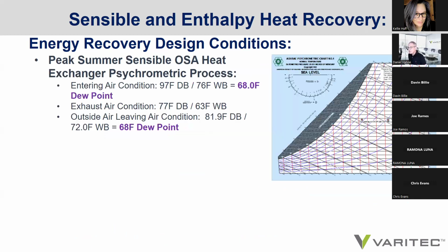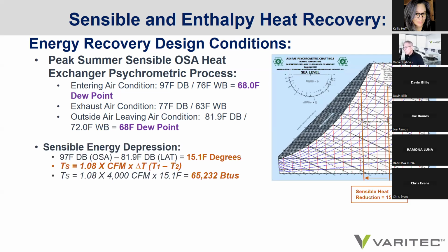So let's look at it psychrometrically, and let's look specifically at the cooling process. If you use a plate and frame sensible heat exchanger, you'll notice that there's a decrease in the outside air temperature, transferring energy from the outside air to the exhaust air stream because of the thermal imbalance of energy. And as we discussed in previous sessions, wherever there's an imbalance of energy, a high energy state always moves to a low energy state.